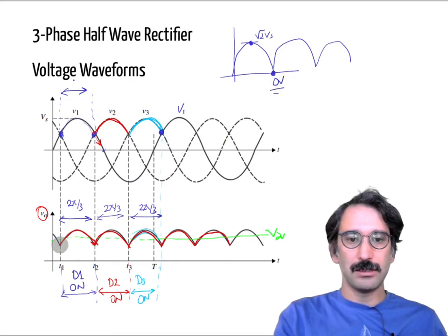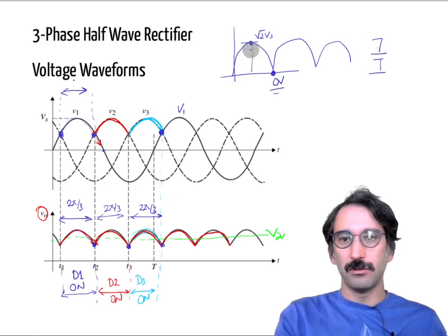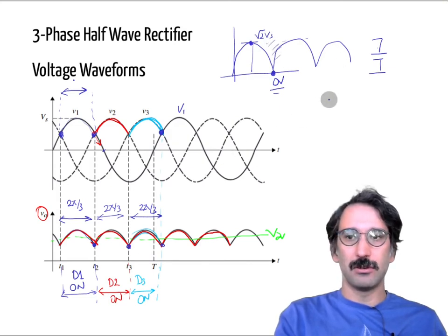However, if you use a three-phase rectifier, the minimum voltage is actually higher than 0 volts, so it doesn't go down to 0 volts. That is good, because if you would like to put a capacitor filter for that one, you have to put quite a large capacitor to compensate for that area.